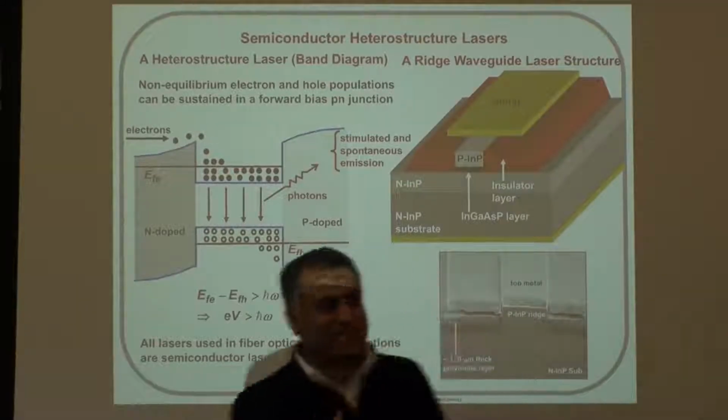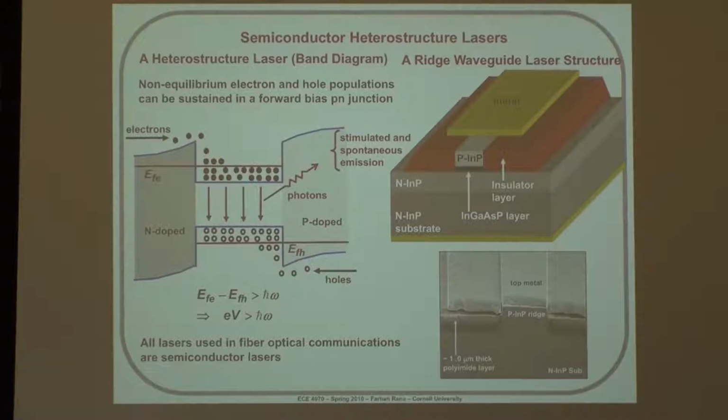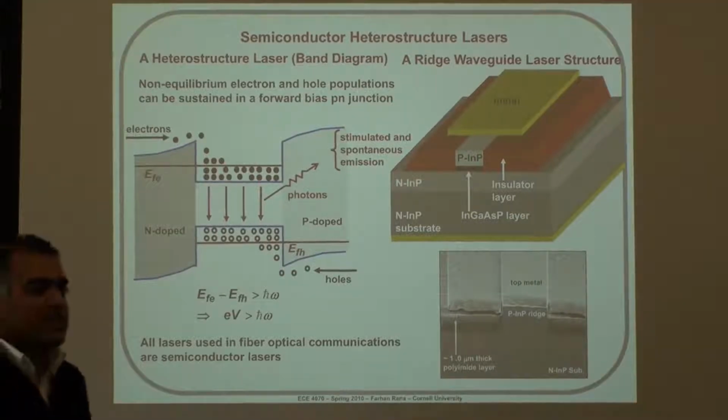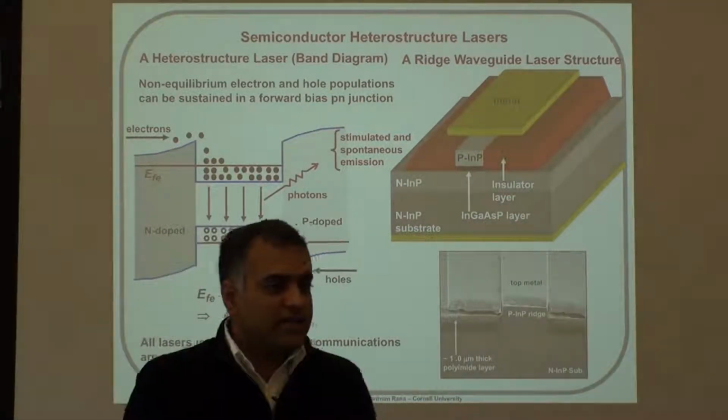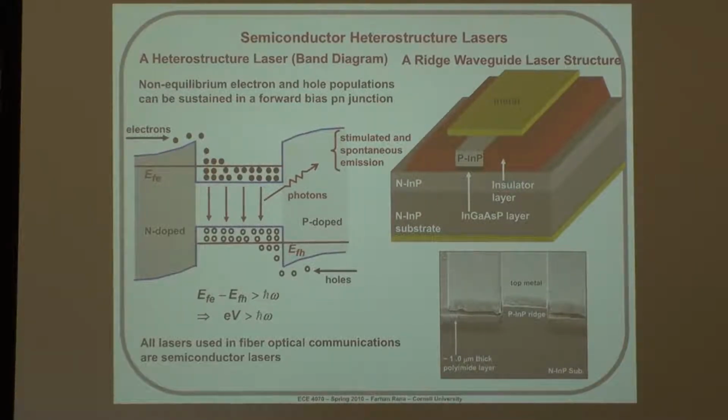Two questions. Okay. So the band offsets in these semiconductors, can those actually change if you're working with correlated materials? I think that answer is not known today. If I have a correlated electron solid, whether the band offset depends on voltages or not, most likely it will change because you're changing the band structure, you are opening up maybe a Mott-Hubbard gap or something like that. But in semiconductors with single particle physics, it does not change.